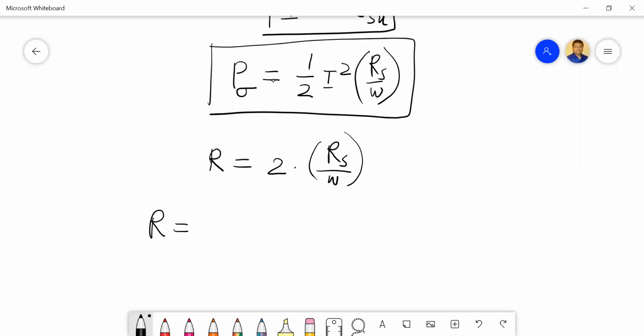Or we can also guess, because the ohmic losses are due to the plates, and the plates are running in the z direction, correct? So when we make its equivalent circuit, the R will be coming in series. I'll explain another way in the coming classes. So finally R will be 2 by W, this is W, don't confuse with omega, because omega we write in terms of 2 pi f, that is why.